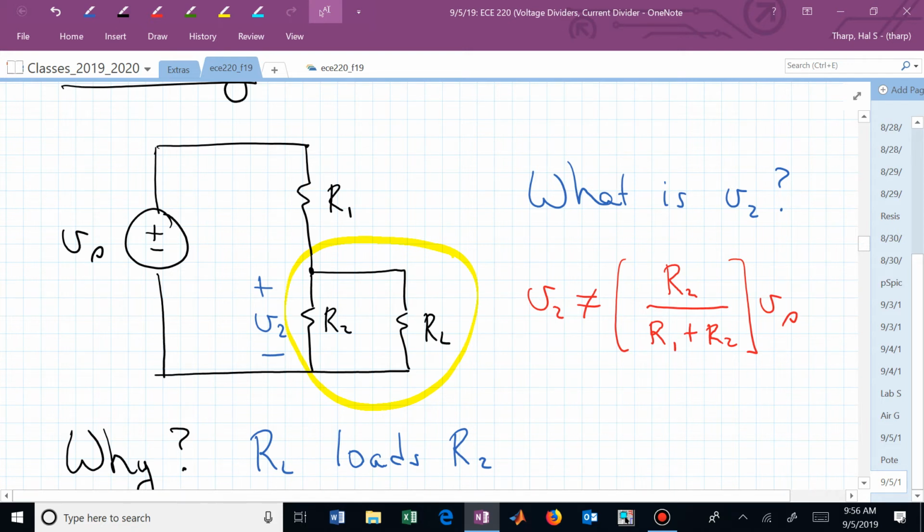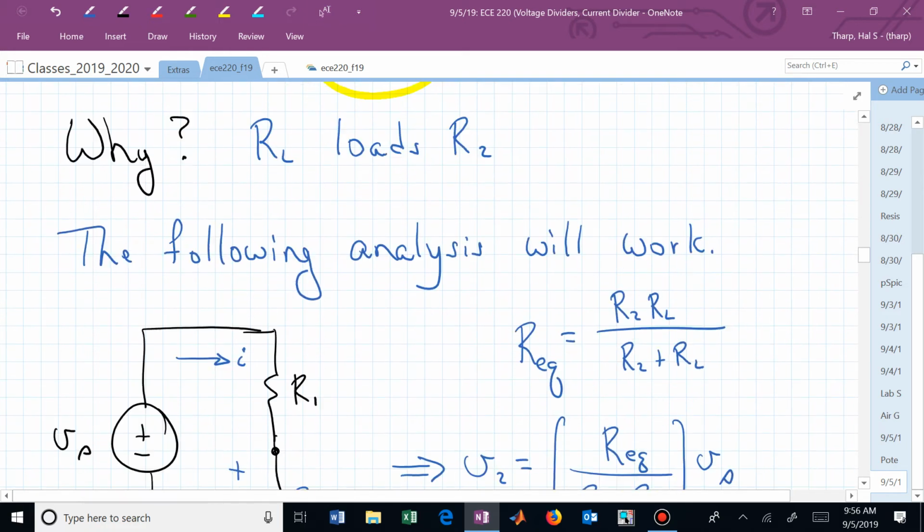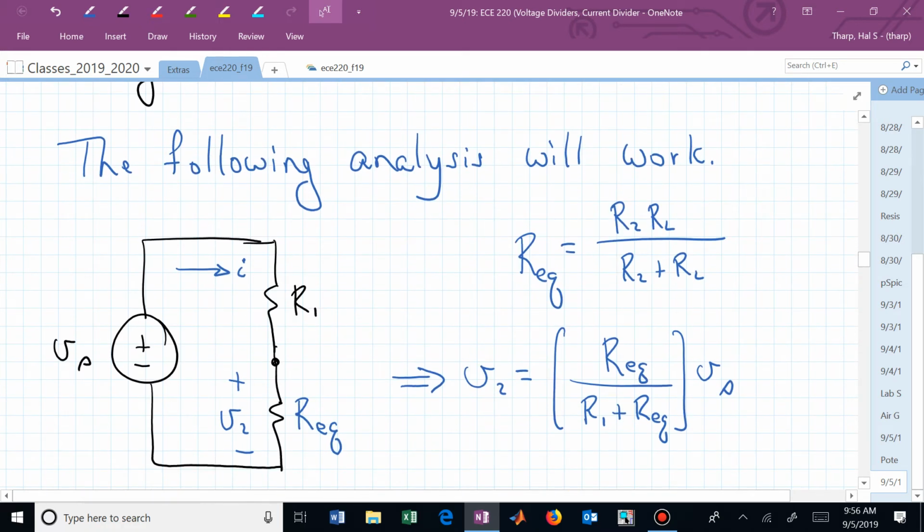It's just that V sub 2 is not the traditional, standard V sub 2 from the standard voltage divider with 2 resistors that I wanted to cover again. Now we have 2 resistors with a load resistor attached, and that's what messes it up. But it still sees the same voltage V sub 2, but that voltage is not this V2 in red, it's this V2 in blue.